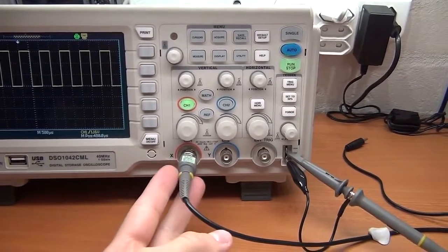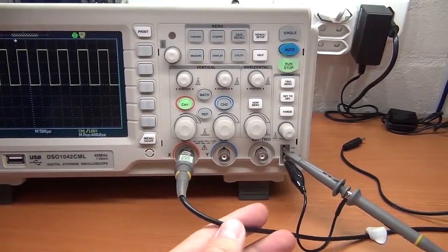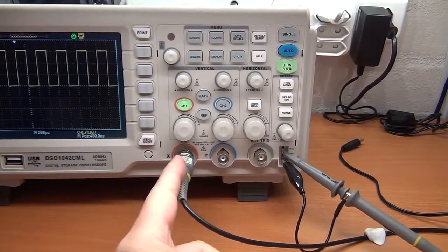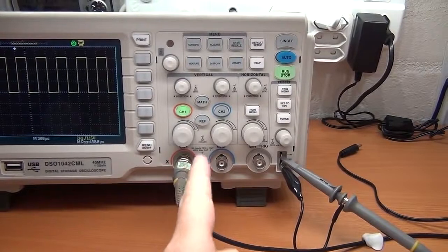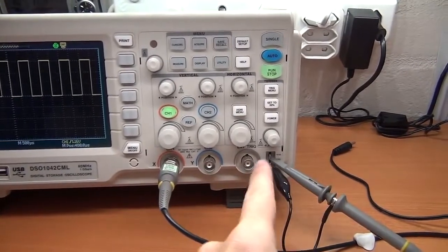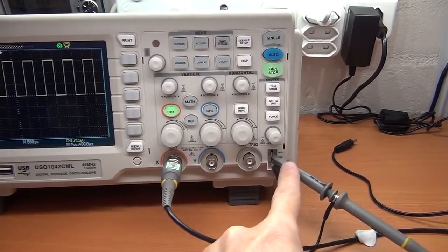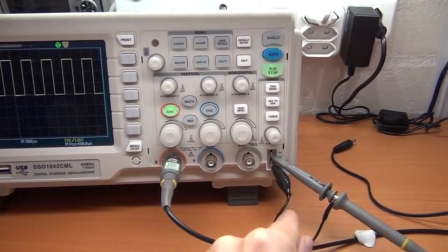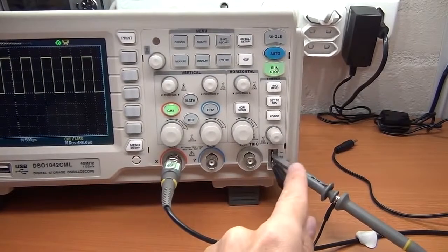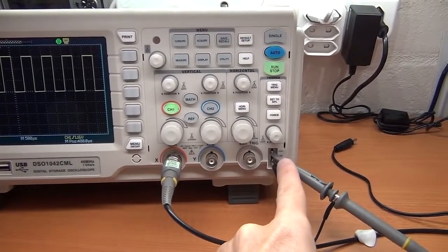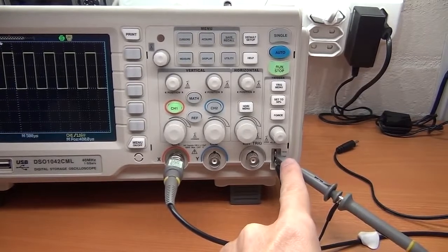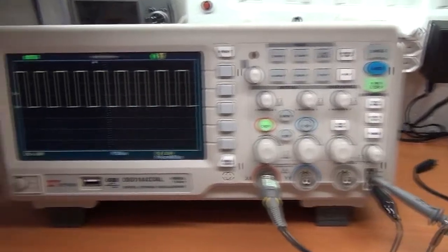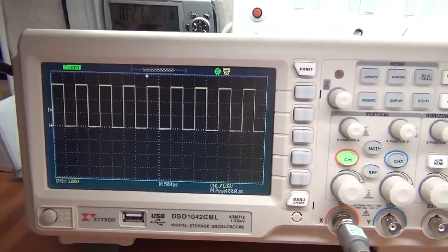But your oscilloscope probe is where you're going to pick up your signal. This oscilloscope happens to have 2 channels. I'm just using 1 channel, which means we can actually view 2 signals at the same time. Your probe is what you connect onto the signal you're measuring, and then you have another lead, which is in essence the ground lead for the signal. So I've got these connected to a reference signal, which you can use to calibrate your probes, but it makes a nice easy sample signal on the scope itself.